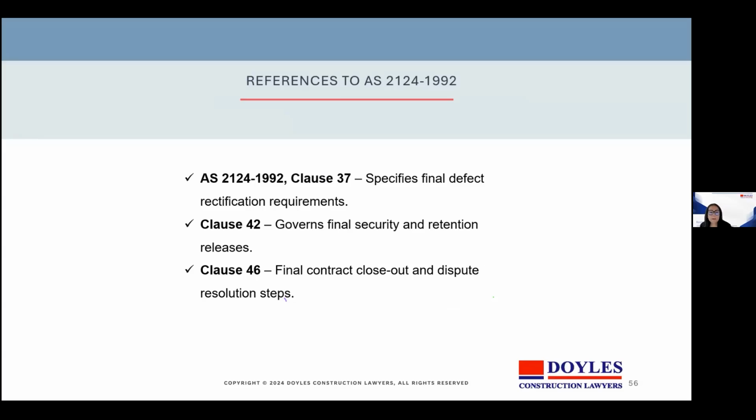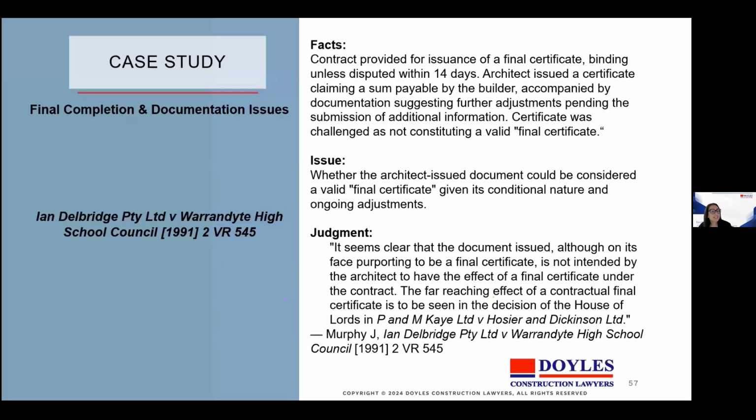So looking at AS 2124 again, Clause 37 specifies final defect rectification requirements. Clause 42 governs final security and retention releases, and Clause 46 final contract closeout and dispute resolution steps. This is a final risk management stage under the contract. Just moving on to a case study now relating to final completion and documentation issues.